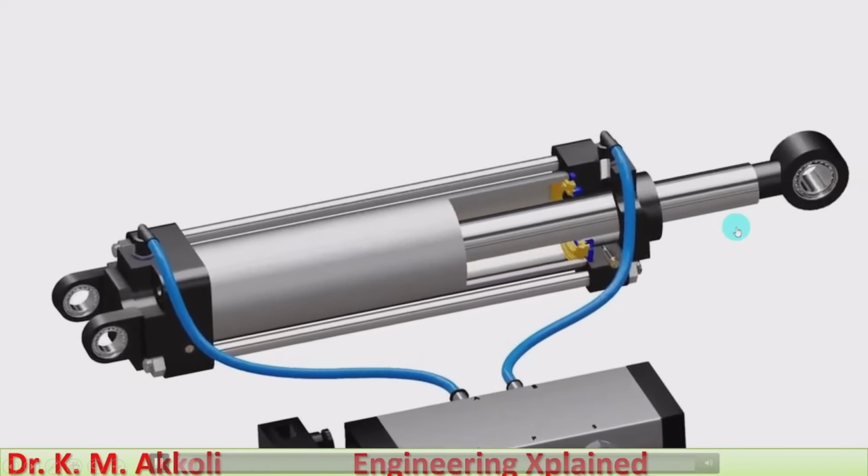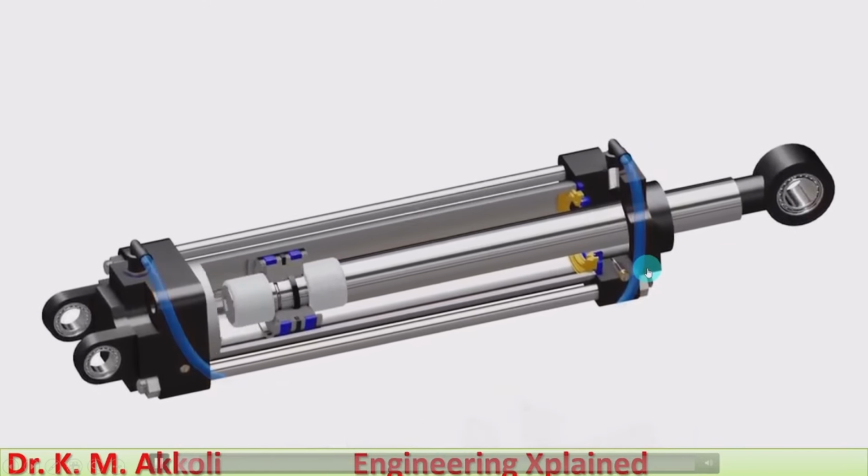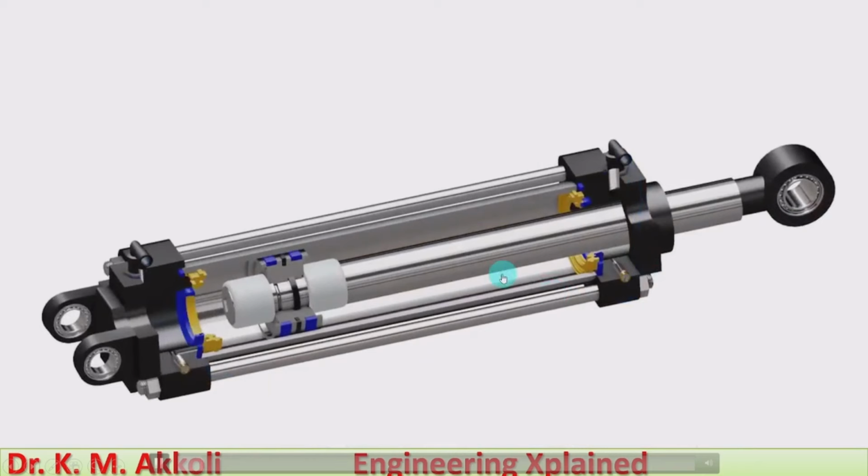producing the force during its extension and retraction. It consists of the cylinder rod, and there is a piston rod, and the piston rod usually carries the force during its operation. It consists of the cushioning piston which reduces the impact force during its end motion, and the piston, which is connected on the piston rod and will reciprocate due to the force difference on either side of the cylinder.